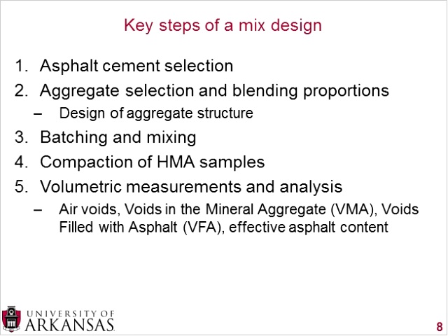Once you've gotten your materials, you need to batch and mix your asphalt and your aggregates, and then you have to compact them in some way. And you'll see 3 different types of compaction theory in this presentation. And then finally, the last step is to do your volumetric measurements and analysis. And this can include performance testing if you wish, but a lot of things that people look at are terms like air voids, voids in mineral aggregate, or VMA, voids filled with asphalt, or VFA, and effective asphalt content. So when we look at the 3 different mix design methods, we'll see these same key steps repeating for all 3 of them.